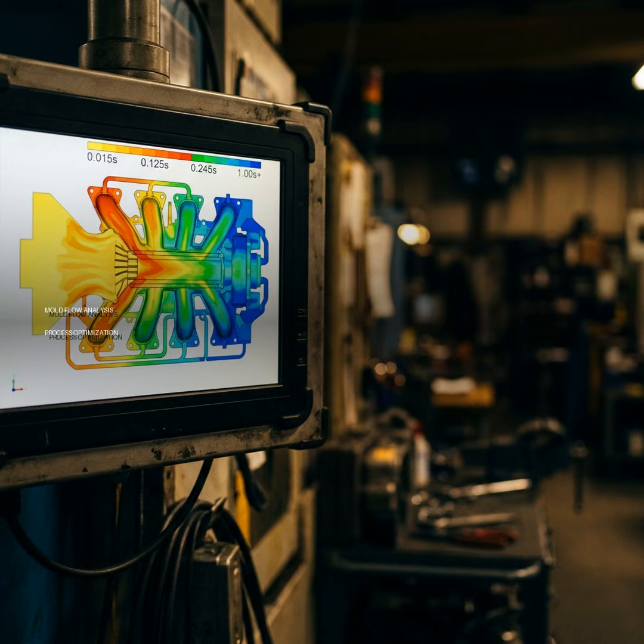That's a huge one. What about those common defects, like air traps or weld lines? Does the report specifically call those out? It does. For air traps, the analysis accurately identifies where material flow converges and traps air pockets. If they're on the parting surface, we know we need exhaust slots or vents. We might need to adjust wall thickness or sprue position. Weld lines are similar. They form when melt fronts converge or separate and recombine. The report visualizes these, and we can then look at reducing injection gates or modifying gate positions or wall thickness to improve them.